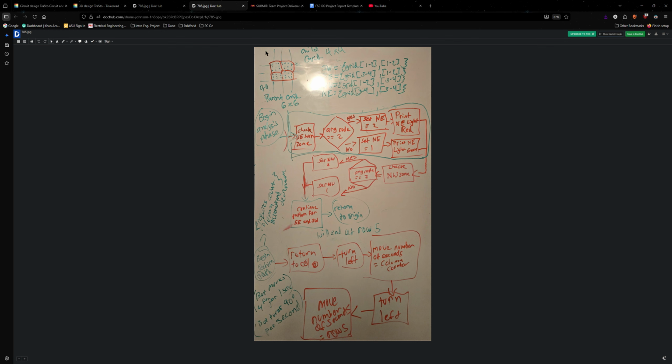The big grid is essentially just the perimeter. So it's where it starts and it's where it'll end and come back to the beginning. So it starts at 0, 0. It'll move to 1, 1. Well, first it'll scan and see if there's any debris in the way. If there's any debris, it won't deploy at all. If everything is fine, it'll move to 1, 1, and then it'll start traversing the grid in a snake-like pattern.